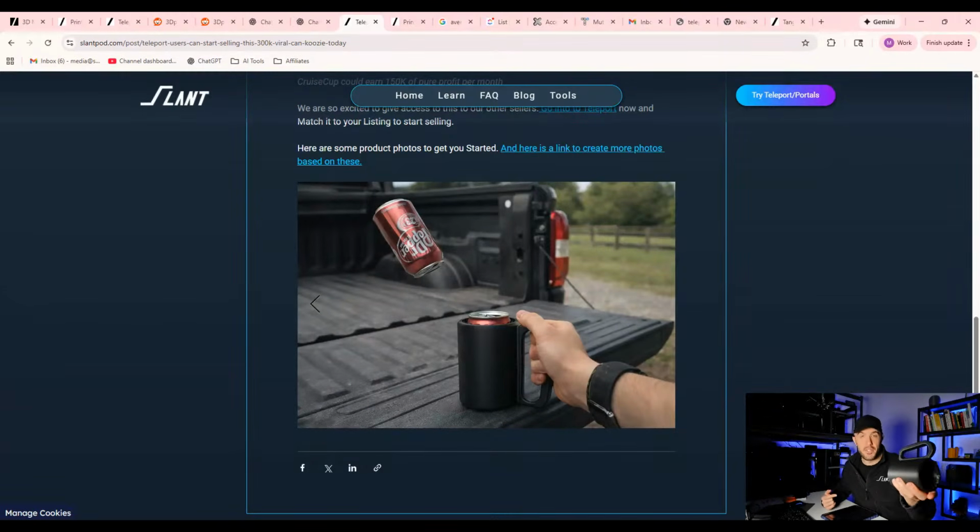Because if you're a file designer and you're sharing the file with a bunch of people, not all of your people will have the same printer. But if you design with a particular tolerance for your slicer and your material, because like this brown will have a different tolerance than this black, if you don't design it so that it works universally, then if you design it just for slicer settings, it will break when someone with a different machine or a different slicer tries to use it. So to create a really good file, you just want to design independent of the slicer. So that's what we teach.